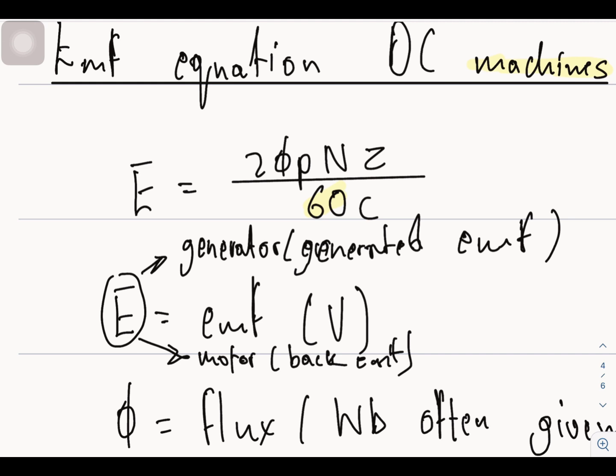That is according to Lenz's law. I don't want to get into too much theory today. But a motor does act as a generator once it starts spinning, but its electricity is opposing the electricity that we are supplying. Hence, once the motor starts to run, it no longer needs a starter, because the back EMF is very helpful.